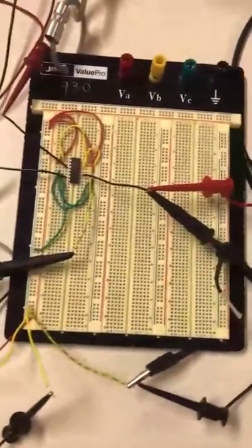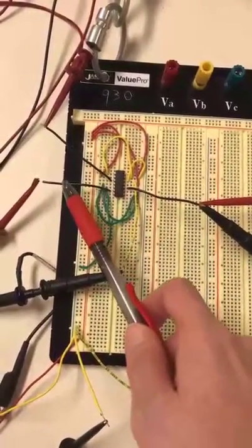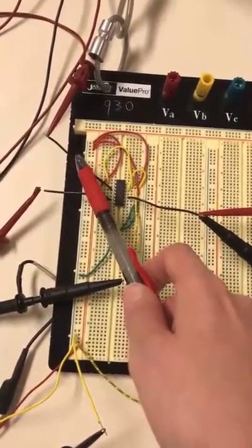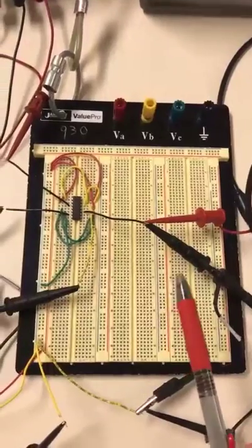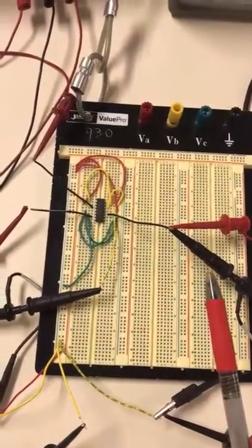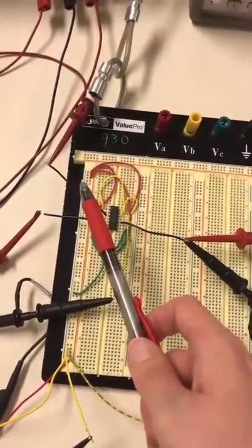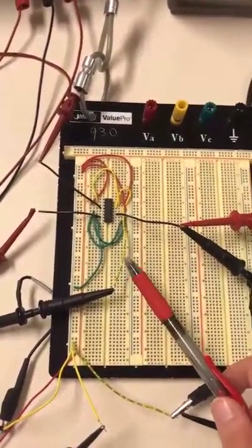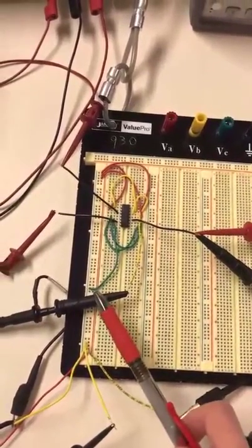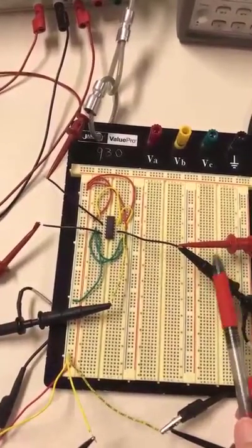So this is the circuit that I built, and this is my IC. The connections are made. V1 is connected to here, this is my V2, and this is V3 that comes from the function generator that is set to generate a square wave with the amplitude of 0 to 5 volts. V1 and V2 are right now connected to the 5 volts DC power supply, and I'm taking the output from pin 12 that I'm going to show in channel 1 of my oscilloscope, and V3 is connected to channel 2 of my oscilloscope.